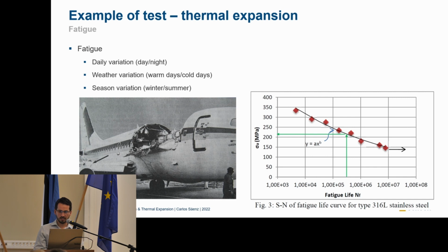So it happens even if you don't reach the plastification, because even if you reach 20 or 30% of your capacity, it will have a real impact after 1,000 cycles. And this is what we do in our tests too. We test that. This is a chart for stainless steel. It's not ours because ours can reach up to 800 MPa.